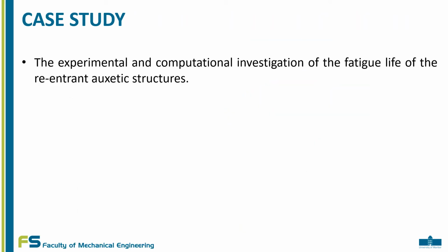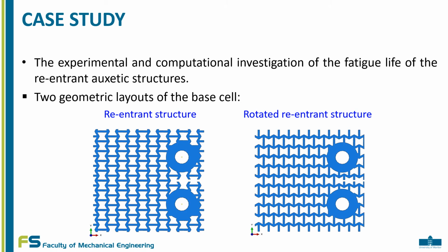The case study is the experimental and computational investigation of the fatigue life of the re-entrant auxetic structures. In this study, we analyzed two geometric layouts of the base cell, the re-entrant and rotated re-entrant structure. The difference between these two structures is in the rotation of the base unit cell.